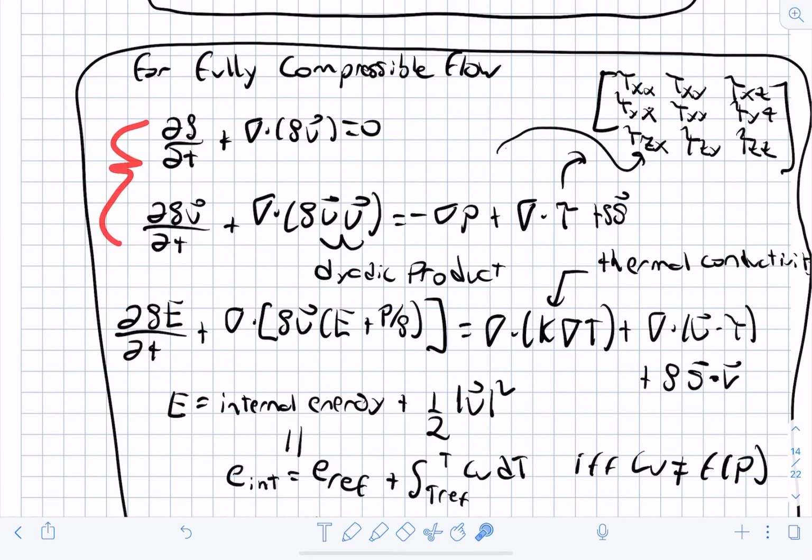And if the flow is compressible, notice here, we have pressure, we have velocity, and we have density. In 2 dimensions, we would have one equation here, and we'd have 2 more equations here, and those extra equations can give us information on the velocity, u and v components, but also we have pressure.